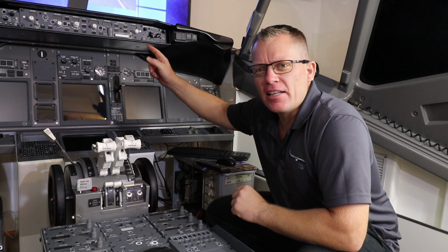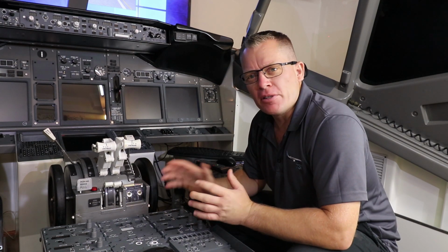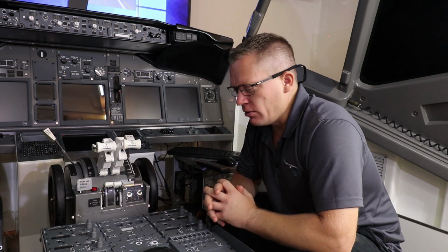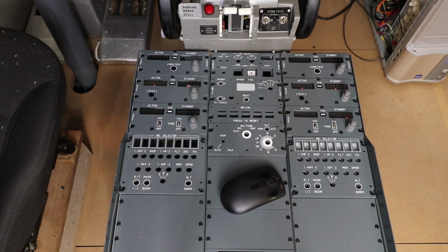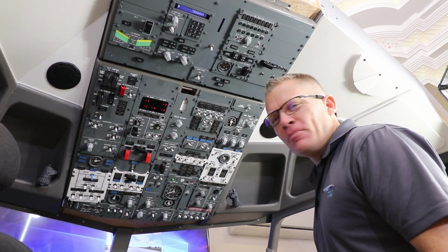Well, instantly you can see that the MCP has gone off, and so has the pedestal panels. Now there still is an issue. I'll bring the camera over, and that issue is the decimal points are still showing on some of the radios and not others. So what I think I'll do is use the precondition tab as well as the -1 to get rid of it completely. So if I stop MobiFlight and then hit run, they should all disappear. That's the MCP, pedestal complete.